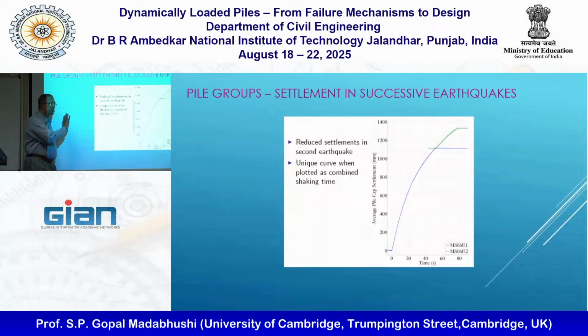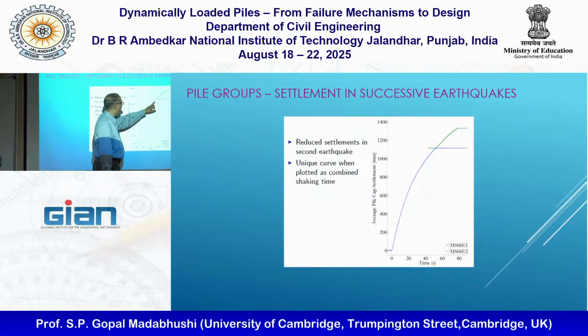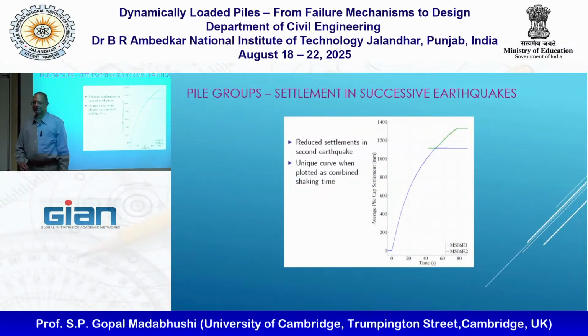This is really beautiful. In earthquake 1, the settlement stopped here. And if I put the settlement I got in earthquake 2, it's almost continuing the same thing. There's no field data, no real data like this. And this is one of the nice things about centrifuge testing.